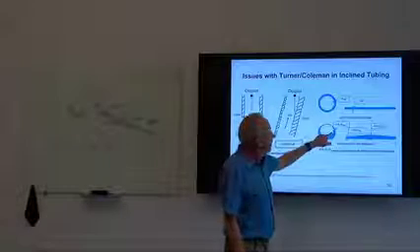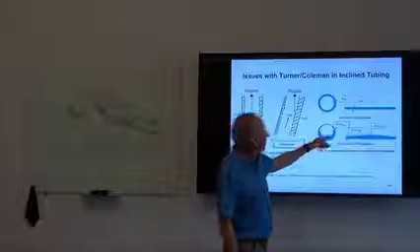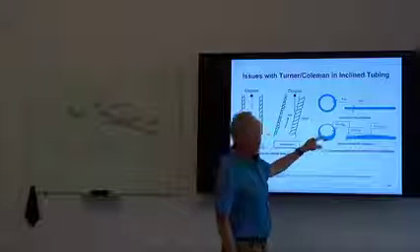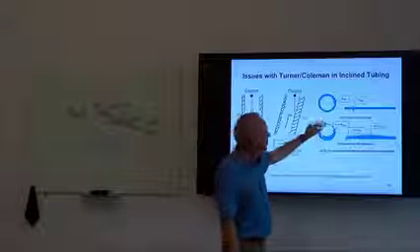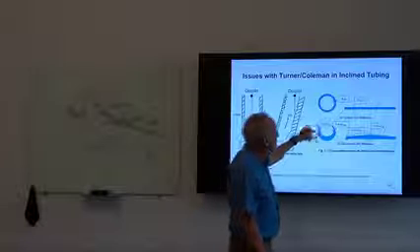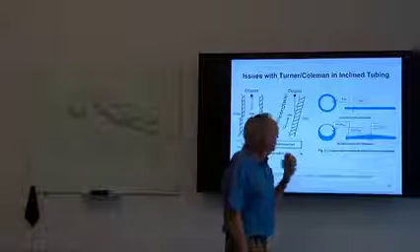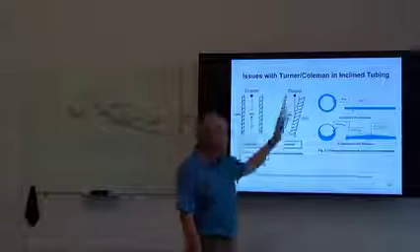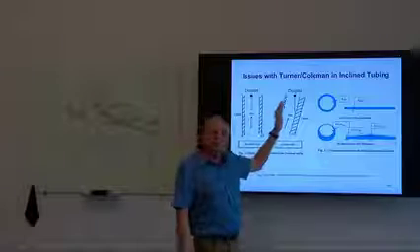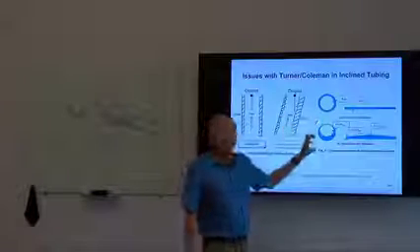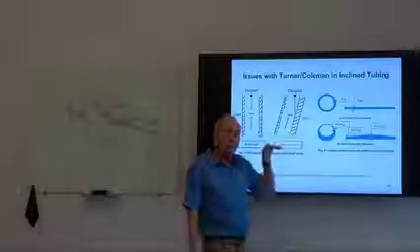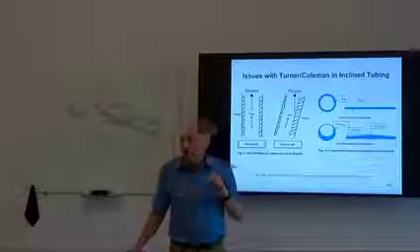So we get a different liquid layer thickness on this tubing wall relative to the surface. So we have this non-uniform film on here. And the more this pipe is inclined, the more this is pronounced, until we really get a very high degree of stratification.